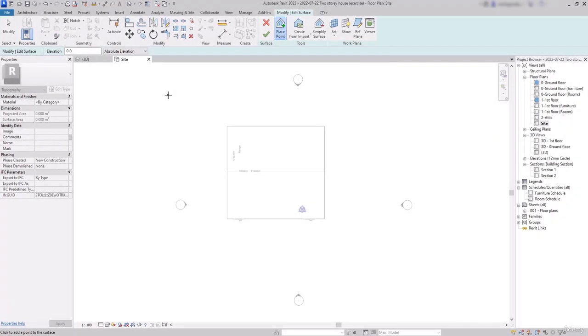At the options bar, you can see a blank to insert the elevation. Currently, it's set to 0, in this case millimeters, because it's the unit that I set for the distances in this project. Let's keep it how it is and start drawing points around the house. While you are placing them, you can see an area being generated to connect them.